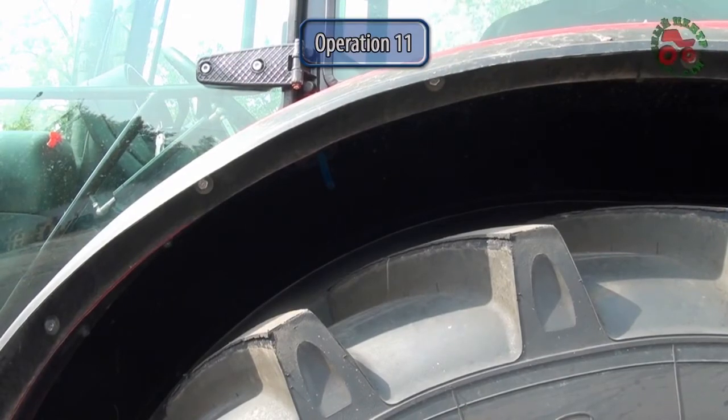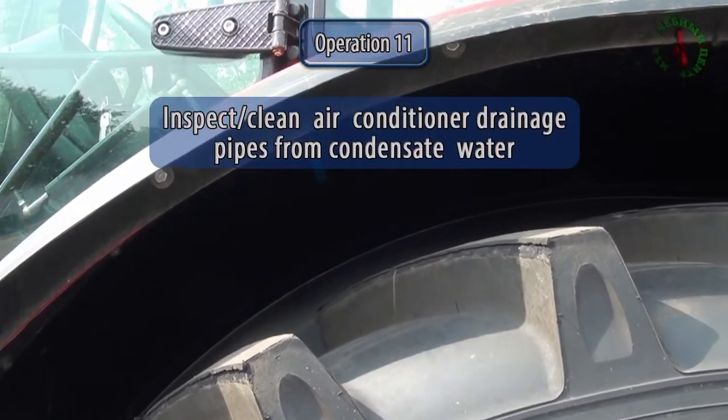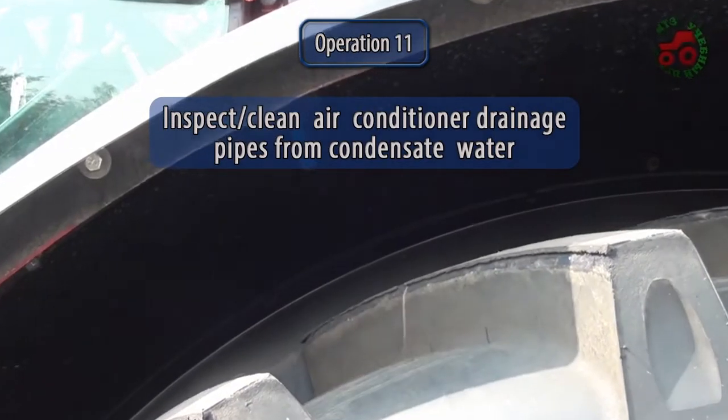Operation 11. Inspect clean air conditioner drainage pipes from condensate water. Light blue drain pipes are placed to the right and to the left of the radiator pipe under the sealing panel. To avoid clogging, the drain pipes shall be checked and cleared when necessary. Cleanness of a drain pipe is indicated by water dripping when the air conditioner is used in hot weather.